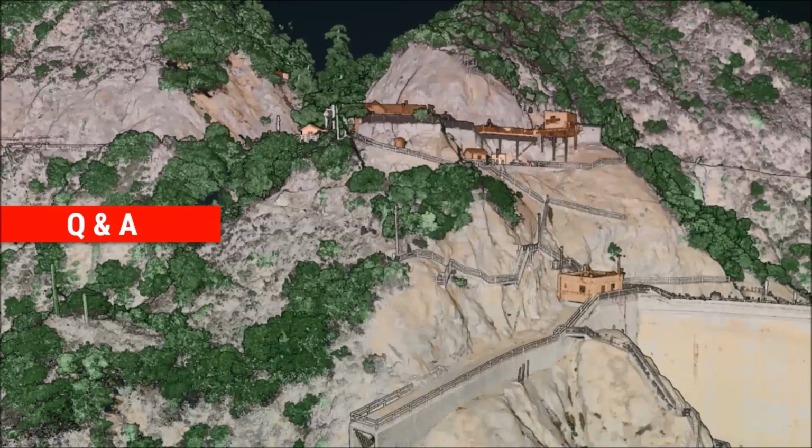However, there is relative within-image variation that can happen, because there are 640 pixels in the Nano, and they can drift independently from each other. And so we actually do a dark electrical image collection, and we can do that as frequently as we want, because basically we just are in pitch black. We run the camera with the lens cap on, we run it for a minute, and then we turn it off.